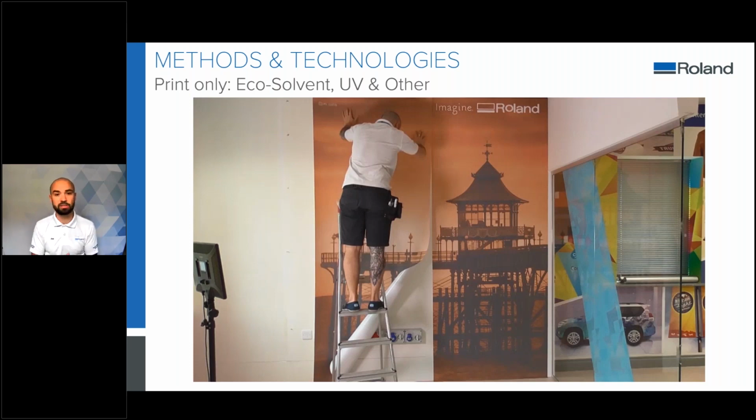The reason you have an overlap is that normally the materials that you will use can change over time. They can shift ever so slightly. And if you had a butt-up joint, they might pull apart slightly, leaving a thin gap between them. So if you overlap your graphics, that will not happen. Certain materials will not move.